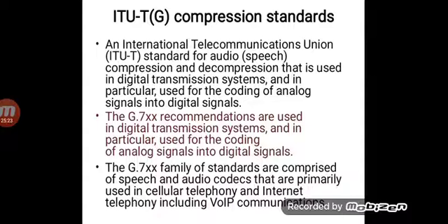And if we go for higher quantization and higher sampling levels, obviously the number of bits which represent a certain amount of audio signal will increase a lot, which causes an increase in the size of that audio file. And there comes a problem when we want to transmit that signal. We need to increase the bandwidth, we need to increase the data rate and whatnot. We need a processor which can process a huge amount of data, piles of data, and that also could create a problem.